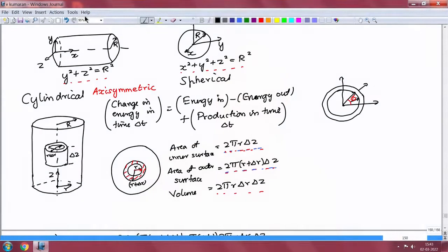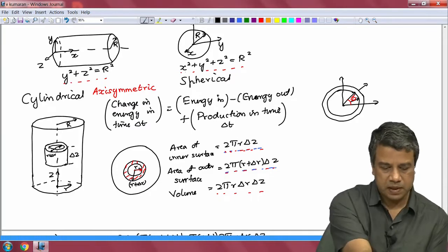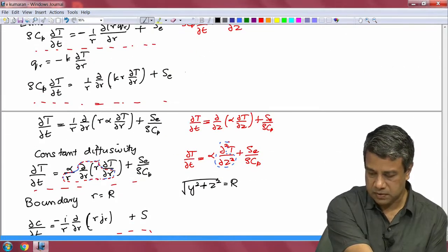We were considering unidirectional transport in a cylindrical coordinate system in the last lecture. We had derived the balance equations by carrying out a shell balance over a cylindrical shell, shown over here, of some height delta z and some annular differential volume between the radius r and the radius r plus delta r. So, these were cylindrical annulus differential volumes of infinitesimal thickness, and for this we did a balance and we got the balance equations of this kind.